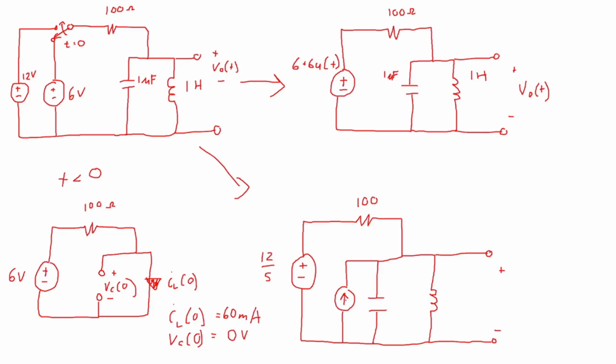And a current source with 0 amperes of current is trying to tell us that no current flows through this 0 ampere source. Well, a 0 ampere source, if no current is flowing, it's indistinguishable from an open. And so while we could write this as a 0 ampere source, it makes more circuit sense to actually say that this is just an open circuit.